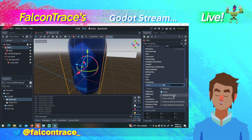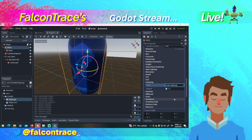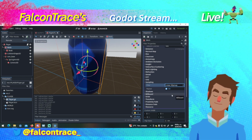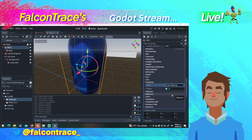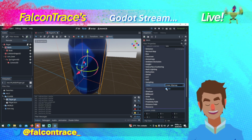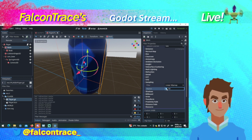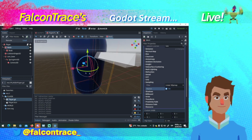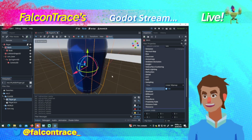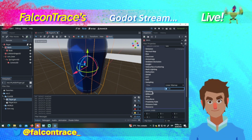You can also choose nearest mipmap, and linear mipmap. Mipmap is an option for better performance. And also you can choose, for example, the option to repeat the texture over here. So maybe you want it to show only once, so you deactivate this over here.